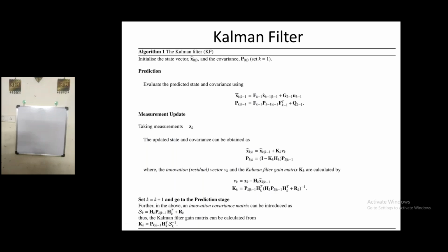So to make the Kalman filter work dynamically, this is very important, there should be some R value. You cannot assume that the measurement noise is always 0. Whatever you do, there will be some measurement noise from the sensors. It could be of the order of micro or nano level, but it is almost impossible to get the accurate measurement from the system.